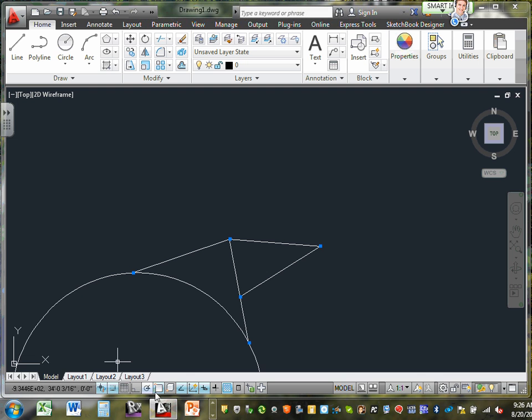Okay. Now snap object. See where it says snap object here? You can snap two objects or turn it on and off. This one is my snap object. I can turn it on or off. On, off, on, off. Can you guys see when you click on it? You can turn that snap on or off. When we are working, sometimes it's nicer to have it off. Typically, if you leave it on, it's easier to attach your devices, your electrical symbols to the walls.